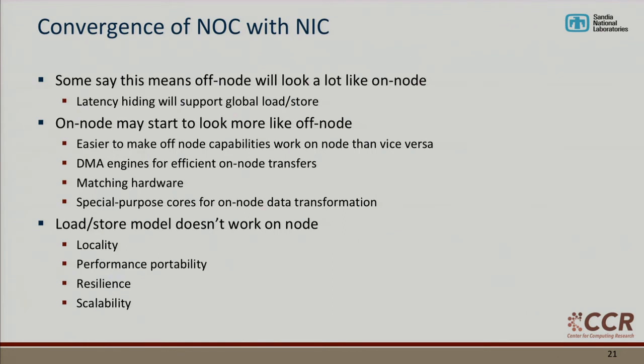And so they're looking at different topologies for how to connect the cores and handle coherence protocols and do things like that with network on chip. A lot of this looks like what you need from a NIC for a large network, for a system level network. And so they're providing things like latency hiding with deep queues in terms of what the processor has, because they need to be able to overlap loads and stores for the network on chip.